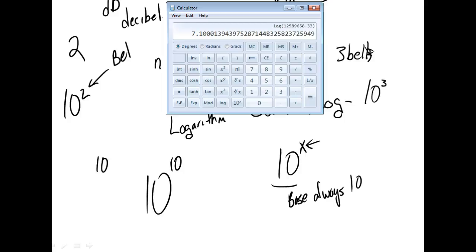So normally when we do calculations, in this class, in DC, you actually measure your resistors because what you're trying to do is prove that I is equal to V over R, and that R is equal to V over I. So what you do is, y'all remember those labs? What'd you do? You color-coded the resistors, you measured them, and in your calculations you used the measured values. And that way you found out that Ohm's law was right.